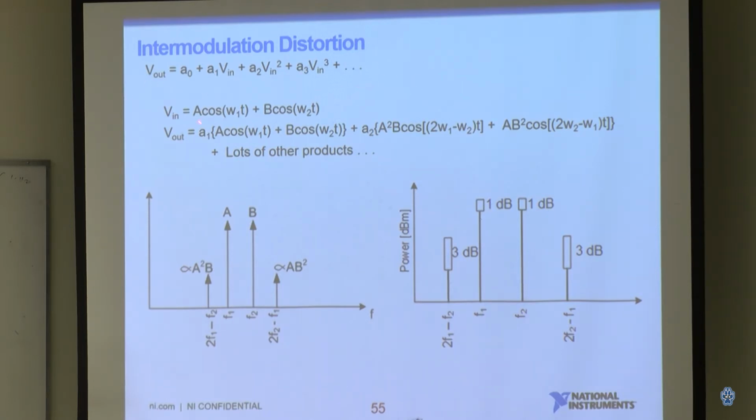Remember, if you have a perfect input signal and a perfect linear system, your output signal will be linear, right? But because your real system is never linear, it always generates harmonic signals. And this, called third order intermodulation distortion, is what people use to calculate how linear your system can go.